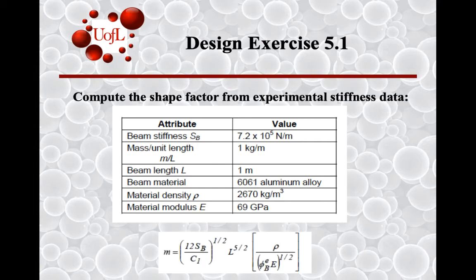We have earlier on derived this equation for minimizing mass as a product of a structural factor in the design, a dimensional factor in the design, and a material factor in the design. And we decided that we could take into account some shape factor by incorporating it into the material factor. So if you know all these, you can find the mass and the minimum mass. Right? To minimize this mass, you would look to minimize this overall quantity or maximize the reciprocal of this quantity.